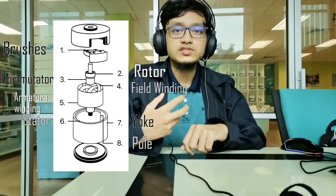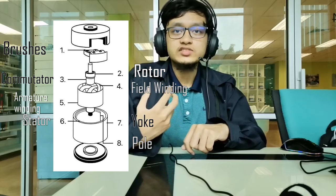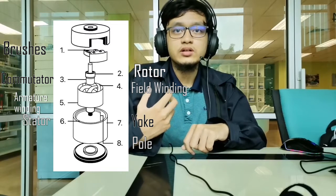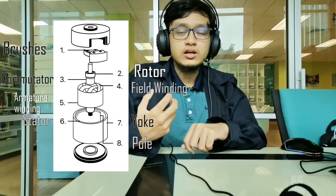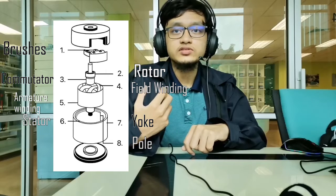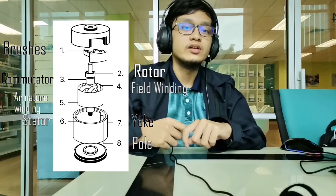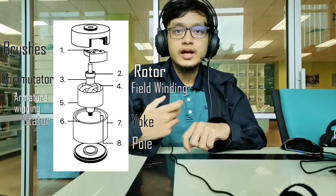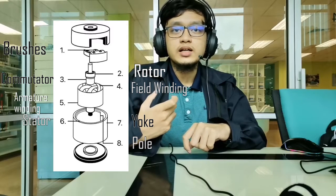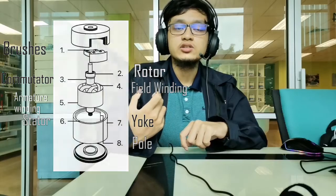And the yoke is a magnetic frame made of cast iron or sometimes steel, which works as a protector. This protective cover keeps the inner part of the rotor safe and sound, and also supports the armature. The yoke also houses the magnetic poles and field winding of a DC motor to help support the field system. And for poles, lastly, they have 2 parts: the pole's core and the pole's shoe. These 2 parts are fixed together by hydraulic pressure and are attached to the yoke.